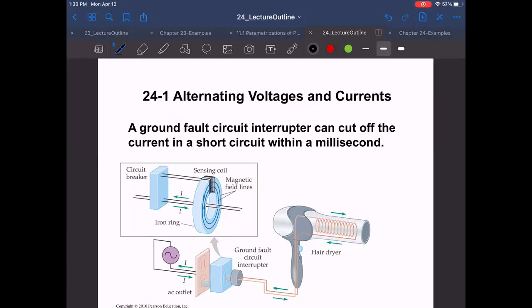You see, if you start to electrocute yourself, say you have a 2 amp fuse in there and you start to electrocute yourself on 1.9 amps, well, 1.9 amps, I believe, is more than enough to kill you. So you could sit there and just be getting electrocuted all day long on that, and the fuse would never trip, or the circuit breaker would never break.